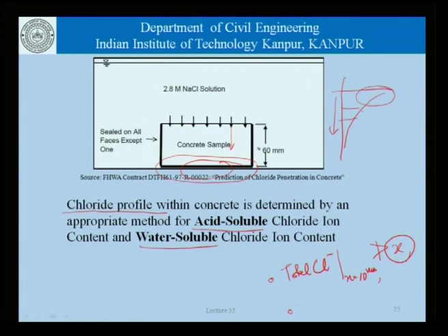Another engineer could say, I would like to have a concrete where the soluble chlorides at x is equal to 15 mm should not exceed a certain number. So, this is what we want to state by saying that we are getting into performance based specifications. We are not talking only in terms of the strength of concrete, but also in terms of the actual chloride permeability of concrete.